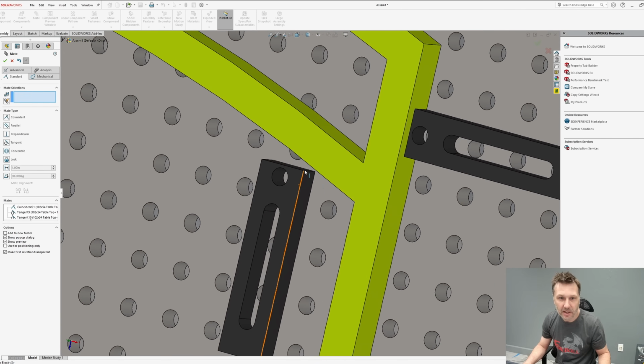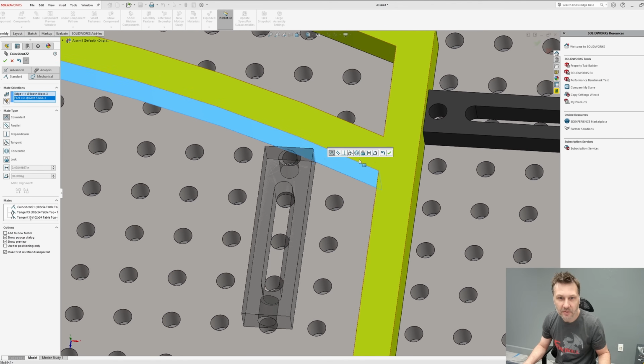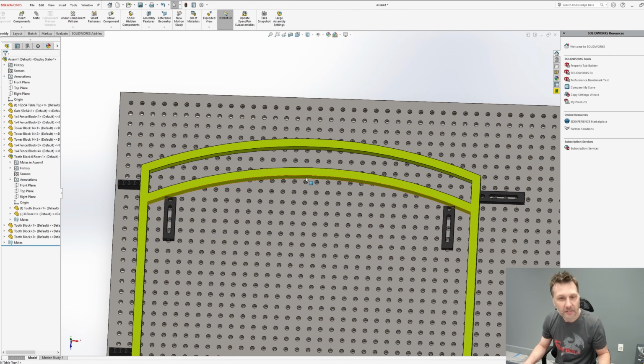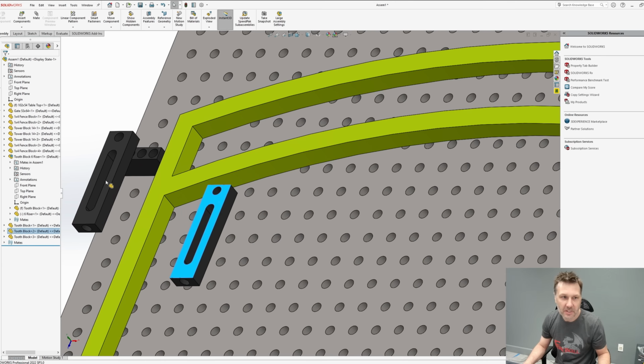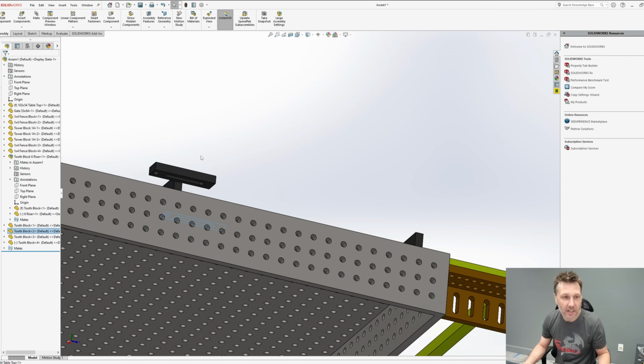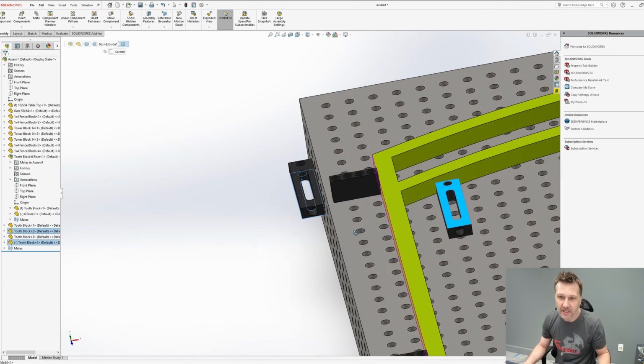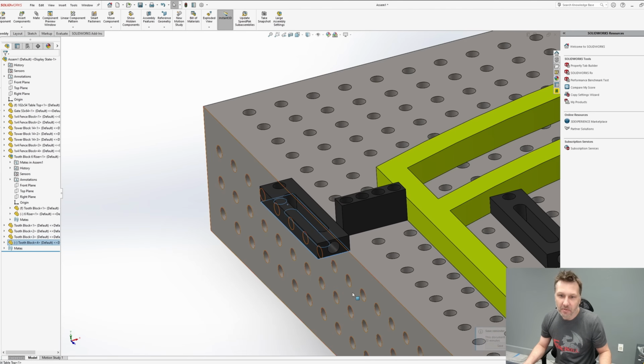And we're going to repeat the process, that corner and this surface. Okay. So there would be 2. You could probably get away with 1 more in the middle, but I'm going to do 2 anyway. This is kind of where it's nice up to the fabricator. If you're drawing fixture maps for your company guys, you probably want to give them more than what they need.